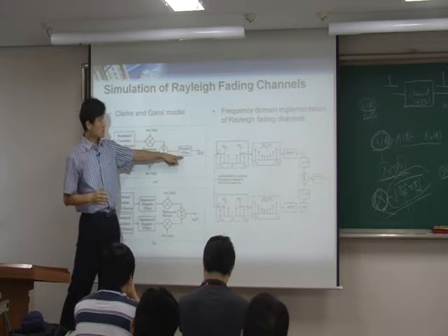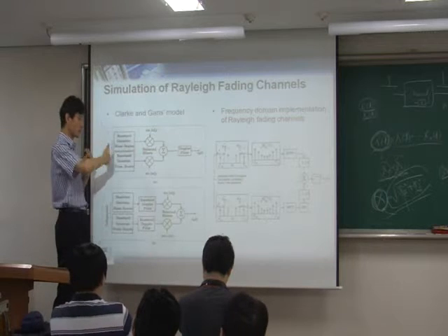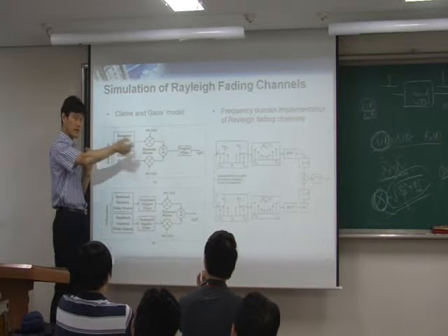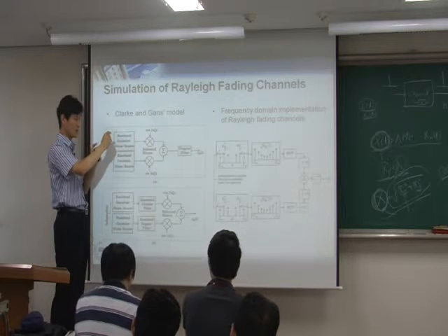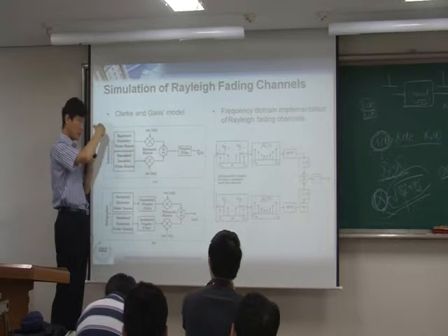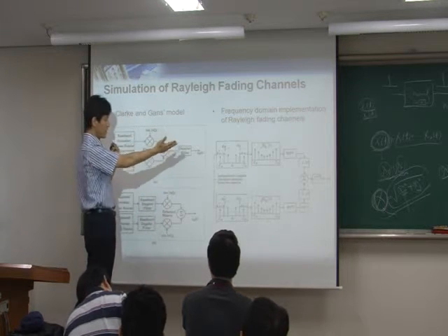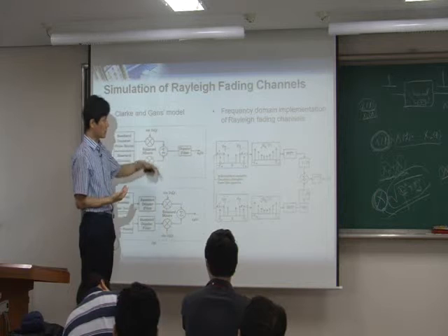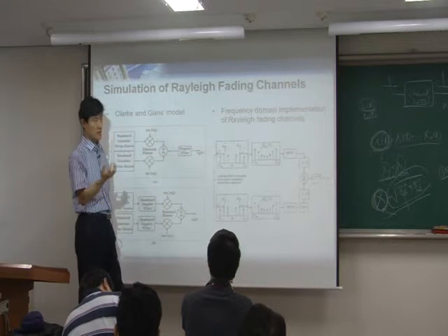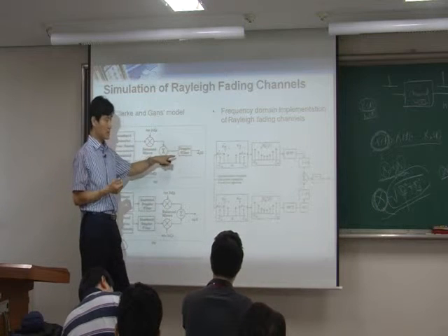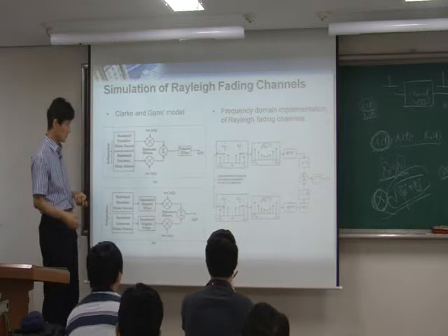You put in a certain filter so that these samples now go through the fluctuation. Each sample follows a random complex Gaussian distribution, but the whole thing, the amplitude, now follows a fluctuation based on the Doppler. So you need to design the Doppler filter. If you have a high Doppler, you design it based on that. Low Doppler, you design it based on low Doppler.